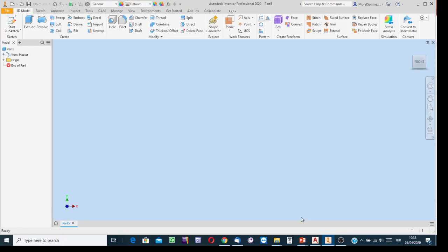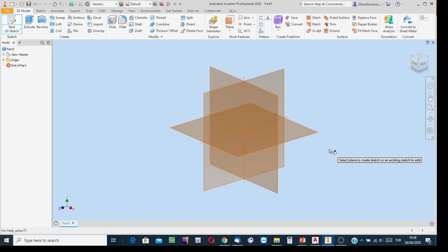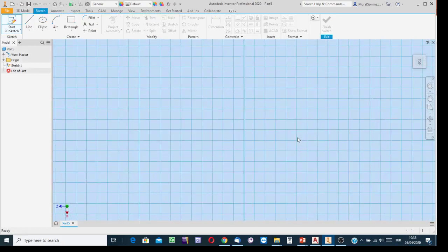Yes. And then sketching stage. Click on the 2D sketch button and select one of the coordinate planes, this or that, whichever you like. It is my convention, I don't know why, but I always select the horizontally oriented one. How? Bring the cursor to the core part of the coordinate plane, and after seeing the color change, click the mouse. You know this.